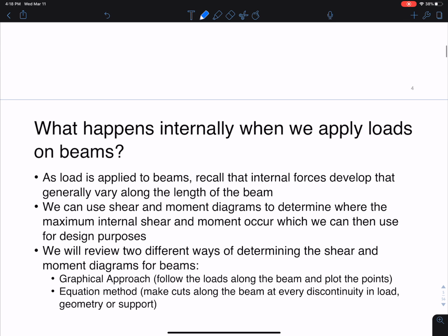So if we kind of think about statics, right, we were interested in statics. If this is our beam and we have some type of loading, we want to find the reactions that this loading causes. We might want to make a cut and find V and M and even N, the normal force, our shear force, our moment that's happening at some cut. This is all kind of static stuff, right?